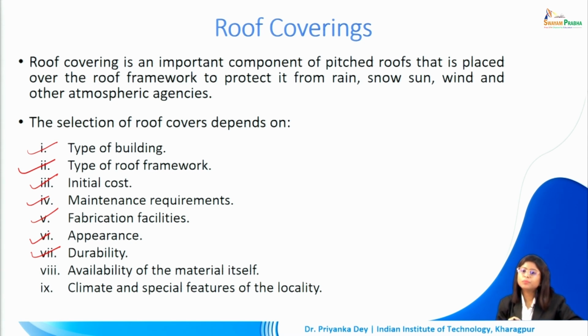Also, depending upon the weather conditions, we have to select materials of higher durability if we are dealing with a far greater amount of rainfall or snowfall that the structure receives. So where we are building our structure, the location is going to be very important in determining what type of material we need to select, whether or not we want a more durable type of roof covering.